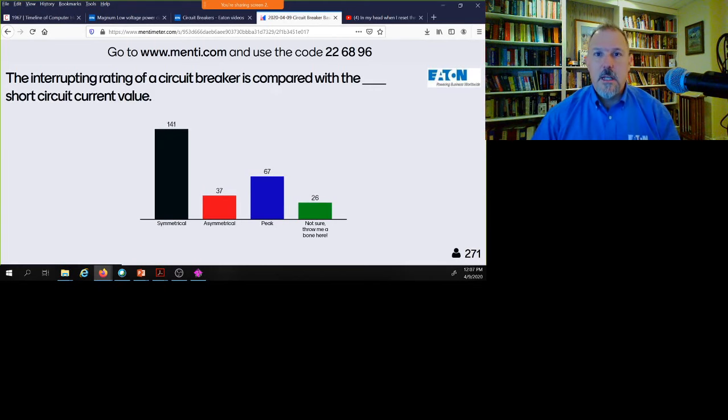That dictates the phase sequencing of the waveforms from a current to voltage perspective. I'm going to show you that and help you understand how we test a circuit breaker, and whenever you apply these devices, what to look for to know whether or not you may have to derate, or you may need to call somebody to get some further information.